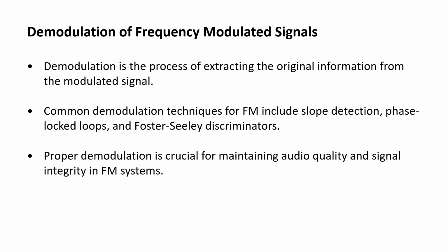Demodulation of a frequency modulated signal. Demodulation is the process of extracting the original information from the modulated signal. Common demodulation techniques for frequency modulation include slope detection, phase locked loops, and Foster-Seeley discriminators. Proper demodulation is crucial for maintaining audio quality and signal integrity of frequency modulation systems.